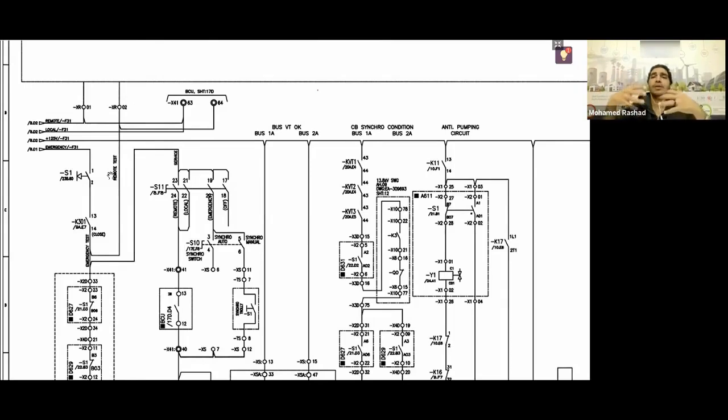There are several ways or forms you will see throughout the Arab world, whether in Saudi Arabia, the UAE, Bahrain, even Qatar, or even Egypt, all right? The idea is quite simply that you have on the cells, either for each one present, it is next to it, all right? Whatever is next to it is close and open. Either you have a close and an open common, meaning that if you press close, it closes whatever is there. How will it know if I want to close the breaker, or I want to close the disconnector switch, or I want to close the air switch?